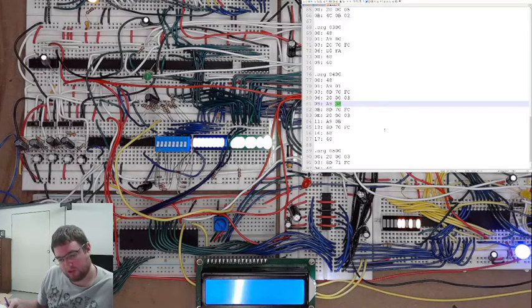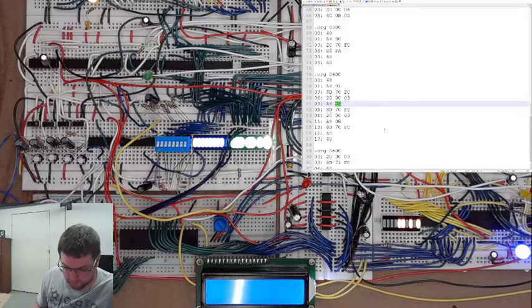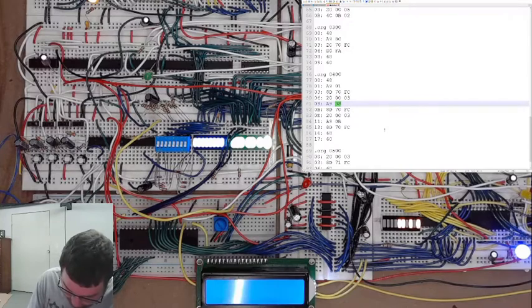So if I'm looking at this, then, well, let's check the display then. For display on/off, we want it to be 0, 0. So it's just the last 4 bits, right, that control this. We want the display on. We want cursor off. And then we want blinking cursor on.